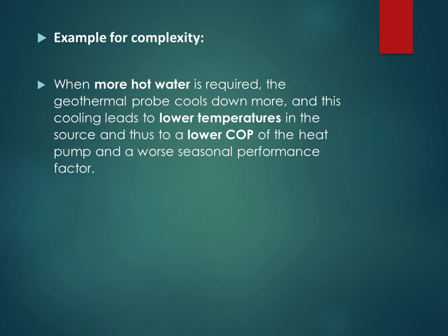When more hot water is required, for example, the geothermal probe cools down more. This cooling leads to lower temperatures in the source, resulting in a lower COP of the heat pump and a worse seasonal performance factor. Simulations can be used to model these complex relationships and their interactions.